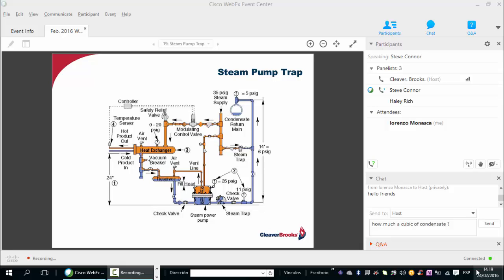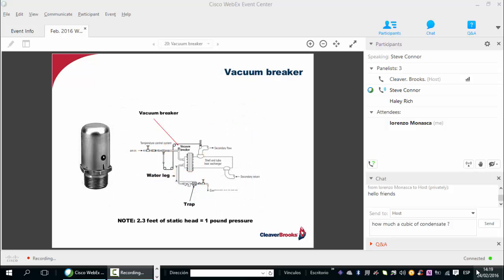Then during full load conditions, where normal condensate levels are present, in other words, that steam control valve is full open, the trap downstream from the steam pump handles this load. So it's only under those low load conditions where the downstream trap has lost its differential that the steam pump comes into play. It works very well and certainly helps that reliability issue and problem that we talked about.